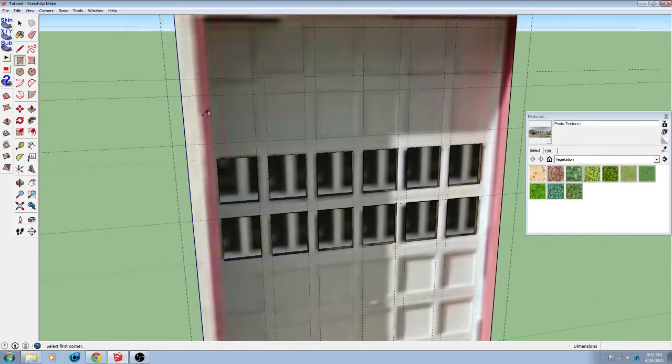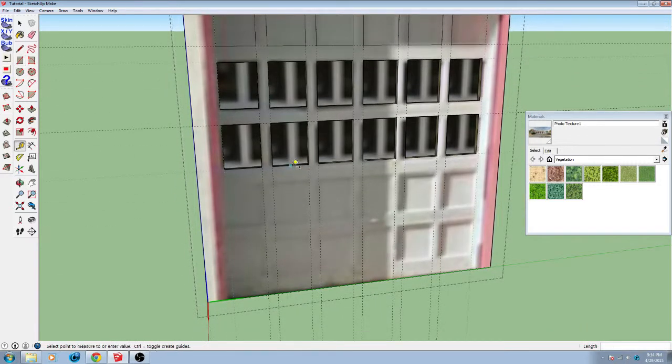And basically we'll just use the rectangular tool here, and we'll connect these as is. So now we have these right here, and come down 0.58, enter, 1.75, 0.58, and well, that last one we really don't have to do.